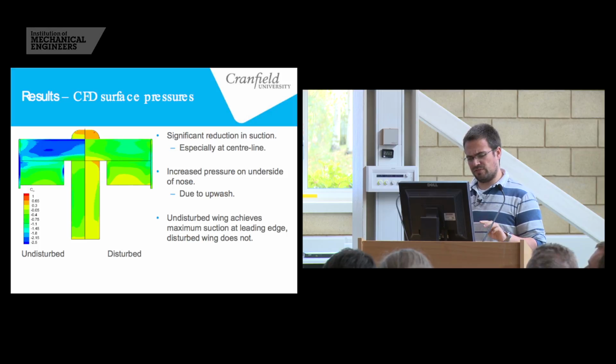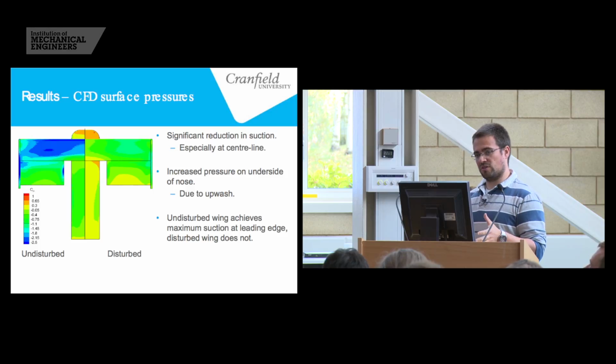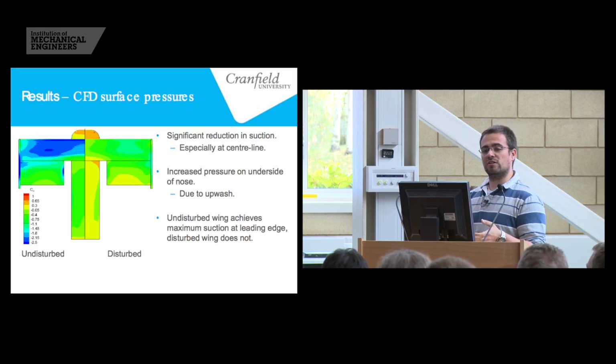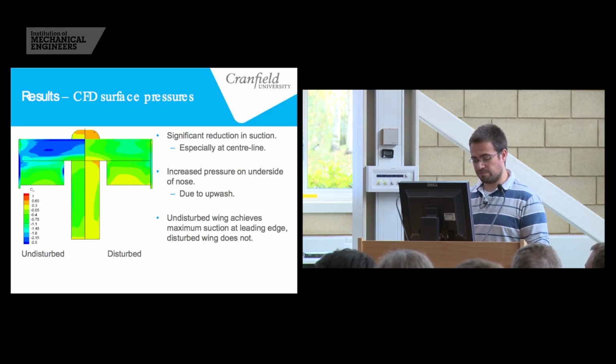We also see a significant change of pressure distribution on the underside of the body that has the force balance inside. This alters the pressure recovery of the front wing, and leads to a change of effective flow angle coming off the wing, which leads to the separation noted at the trailing edge of the main plane.